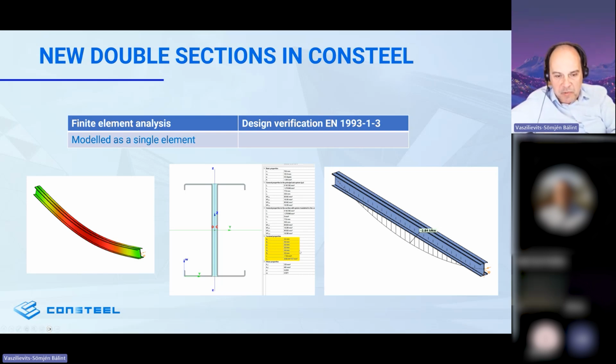So once we are able to define all the properties required for structural analysis to fill the stiffness matrices for the finite element calculation, we can perform exactly the same way the first and second order dynamic calculations and linear buckling analysis, as we always did for single sections.